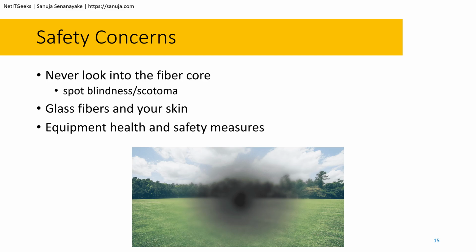And what is that going to do? It is basically going to burn the visual cells in your eye, and as a result, you will have permanent eye damage with blind spots at the back of your eye, and that cannot be repaired. There is no way to repair this as of now in the healthcare field. So please, please, please never look into the fiber core. It doesn't matter whether the optical fiber or fiber optic cable is disconnected, do not look into it.